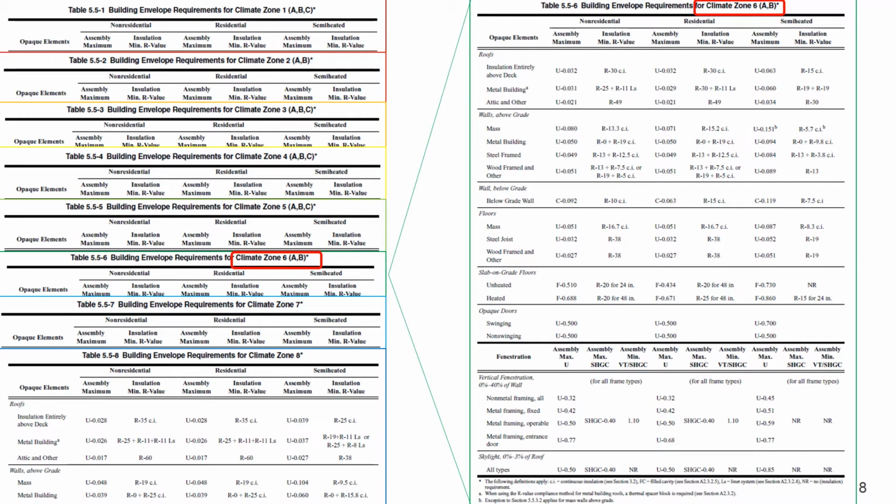You also notice that it is not within the IECC. They combine the fenestration prescriptive information within each of these tables as it varies per climate zone, whereas the IECC had a separate table for fenestration such as windows, doors, and skylights, with window or glazing areas.